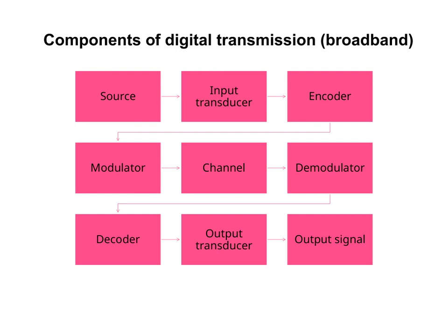Fiber optic cables, for example, are known for their incredible bandwidth and low signal loss, making them ideal for high-speed broadband services. Next, we have the modulation techniques used to encode digital data onto physical signals. Techniques like QAM, or quadrature amplitude modulation, allow us to efficiently pack more bits into each signal, increasing the data rate without requiring additional bandwidth.